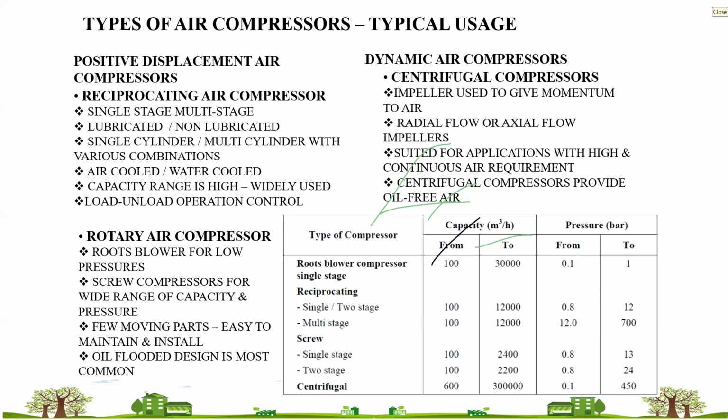But in a single stage compressor, I have to do 1 to 12. So my pressure ratios are on the higher side. So more work has to be done by the compressor, and the motor power or input power will be higher. So your single stage compressors are less efficient than multi-stage compressors.